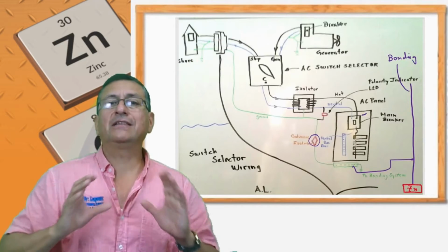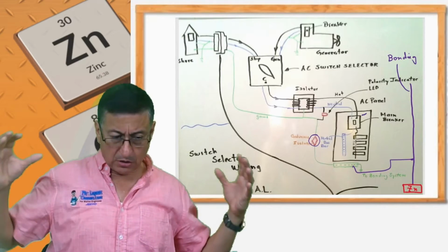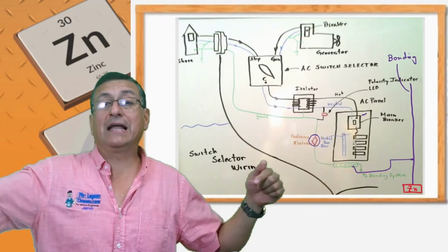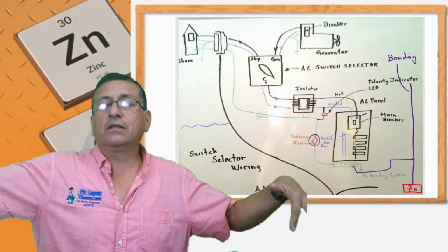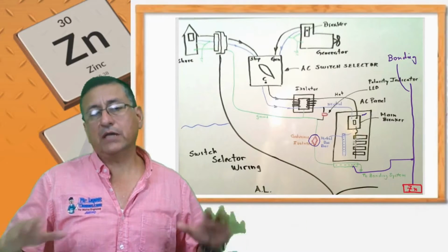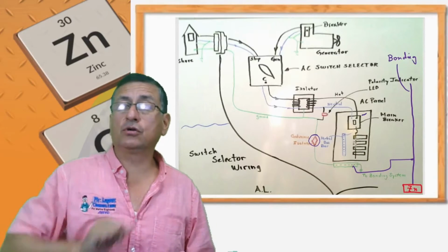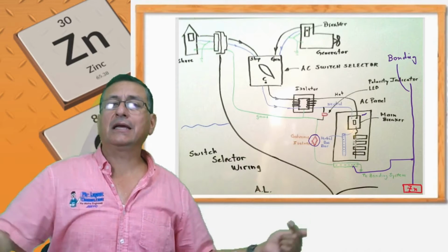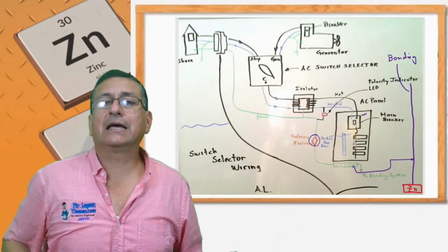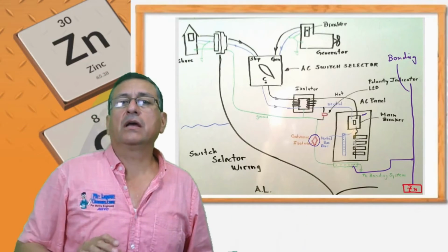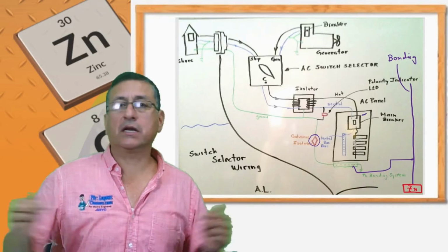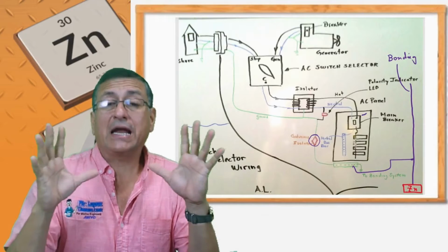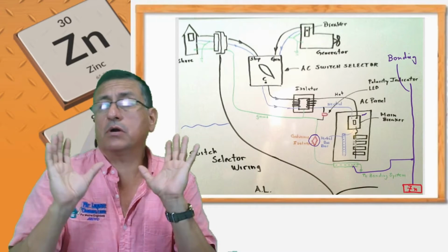The galvanic isolator is the first element to protect my boat from the neighbor boats. Because if the neighbor boats have leaks of current, when those leaks try to enter, my galvanic isolator protects. And also, if the ground of the marina, the ground of the building, is not good, the galvanic isolator keeps that excessive current flowing through the ground from entering my boat. Remember, through the ground, normally the current should be 0.